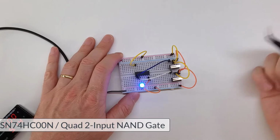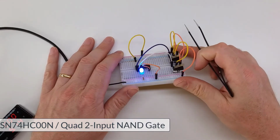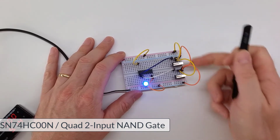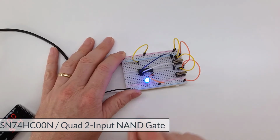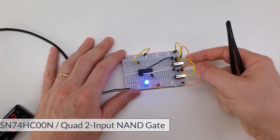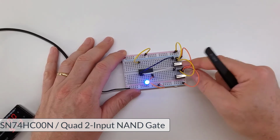And the last chip we've got today is our bonus chip, our NAND gate, our not AND gate. And I've got that wired up, and it's quite simple since it's just got the 2 switches again. The white and the blue are the 2 inputs, and then the blue LED is on the output, which is pin 3. Now you'll notice that it's lit, and the reason it's lit is because both of these are low. So if I take either of these high it doesn't matter.